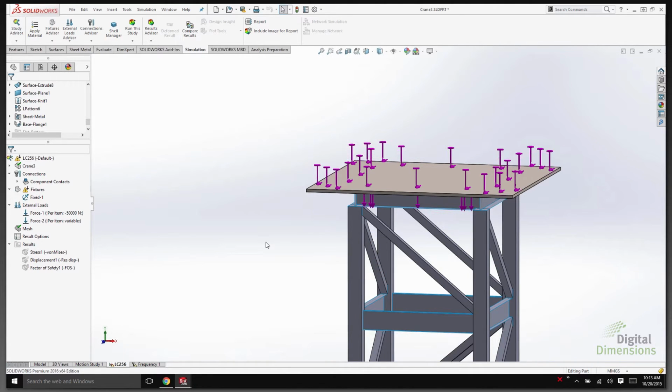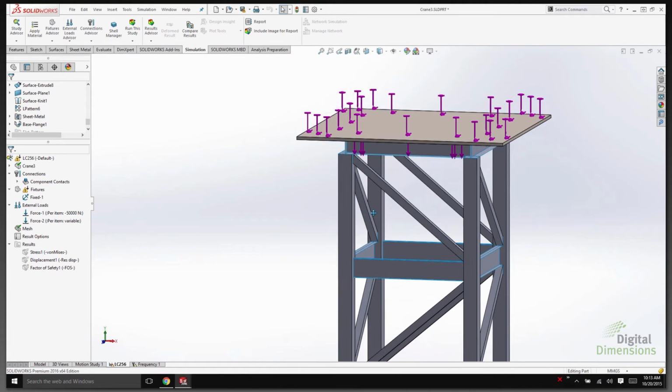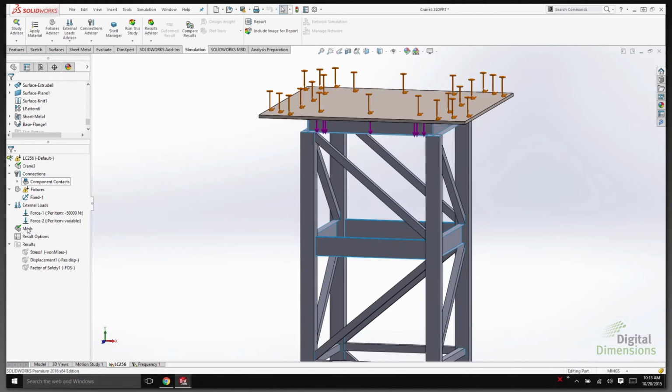But we had to know beforehand how the model was built and that those spacings were present, or we had to go through a different number of steps to figure out which bodies weren't quite present or weren't quite touching. New in SOLIDWORKS 2016, there's an option for us to come in here. I'm going to go ahead and look at this contact visualization plot.